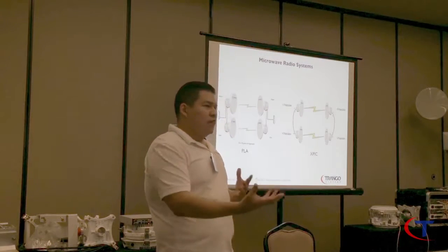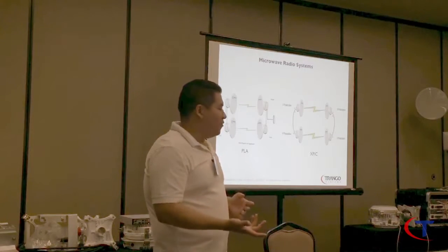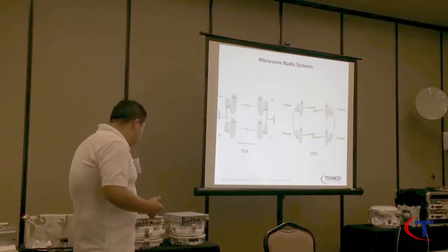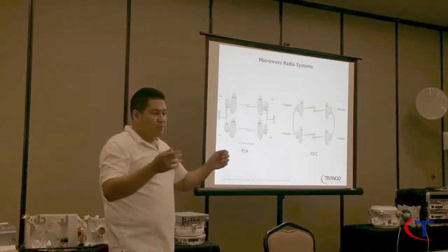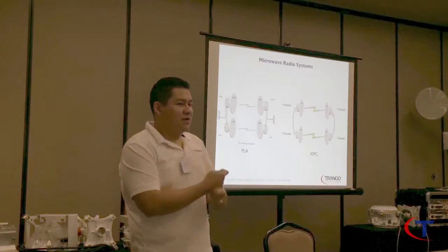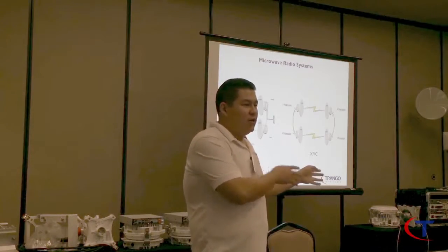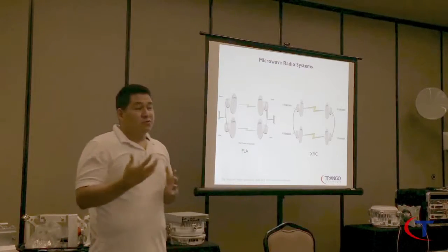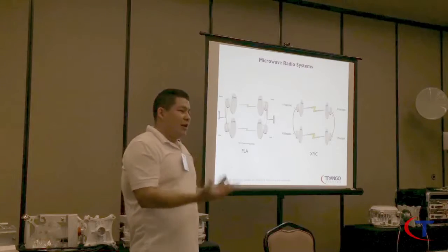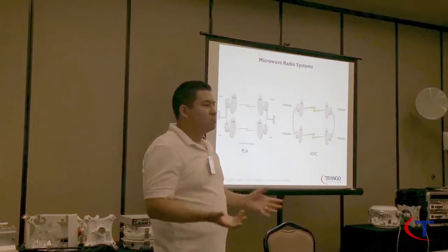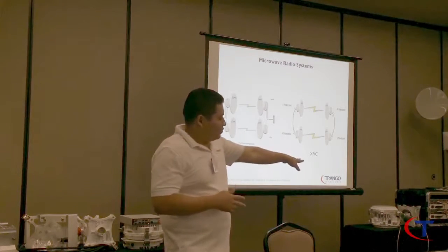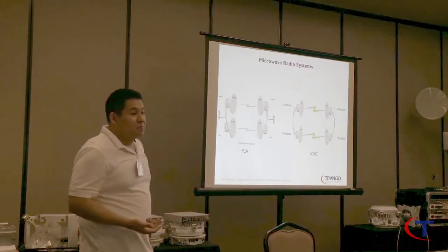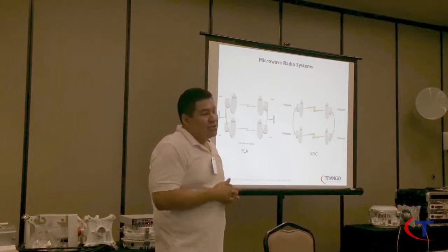So again, for installing purposes, you guys talked before. If I have an all-outdoor radio, which is the Alliance, on my combiner, I don't have two radios, but I want to have a bunch of cables going between each other. In the indoor units, I only have a small amount of cables going between the actual patch panel. And for troubleshooting purposes, if something were to burn out, short circuit, or is acting really weird, you can just go to your shelter, swap out the IDU, and you're done. With this, you have to climb the tower. So, also, ease of use, right?